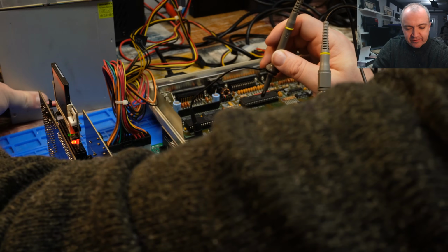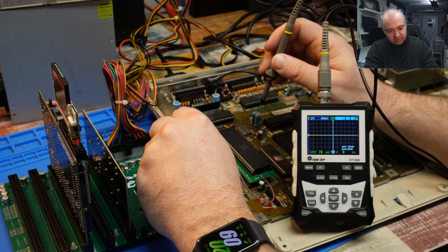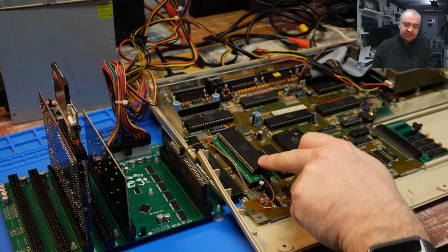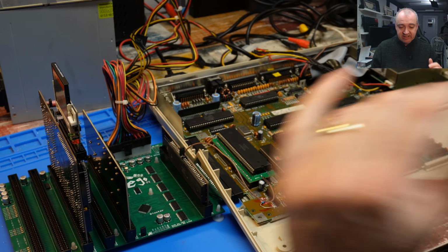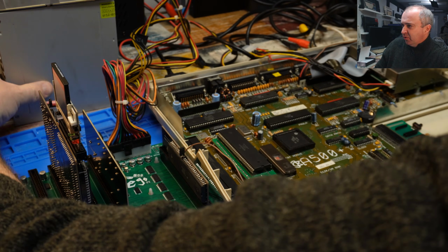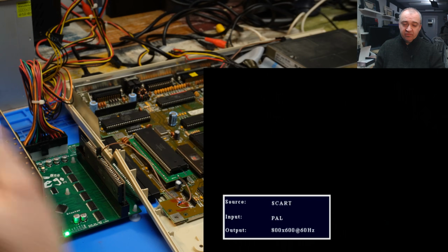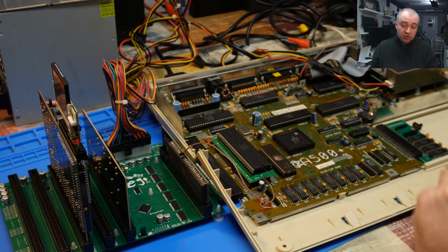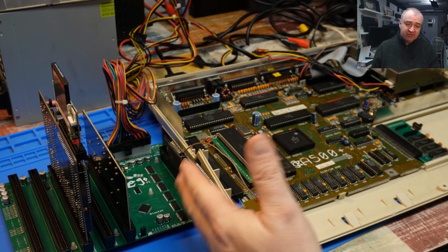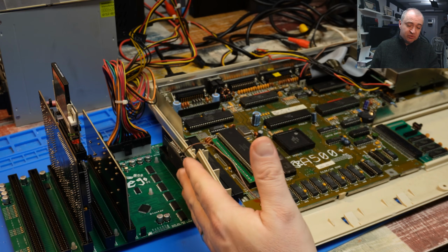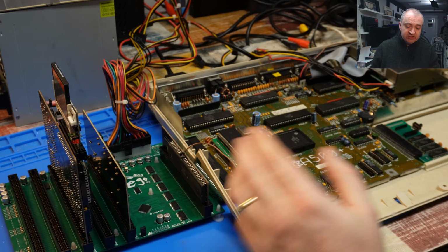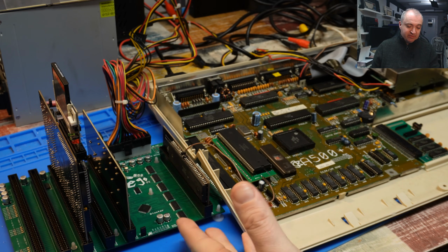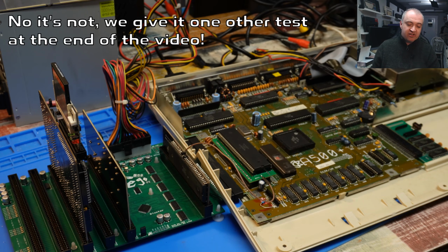If we were to power this off, and if I put that jumper on there, then that CPU will still be tri-stated, but both of them are generating E-clocks. That will clash, and it shouldn't boot. I know, it's just sitting there at a black screen. I think that proves that our BOS board works okay. Now, if you were using a true Amiga 2000 accelerator in here, those things don't try to generate their own E-clock anyway. They'll just take that clock from this chip, synchronized to that. But as I say, that's the only thing I have that will fit into an A2000 co-processor slot or CPU slot.